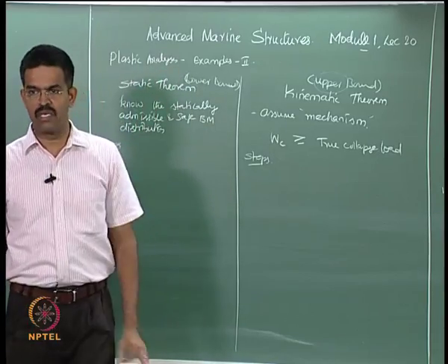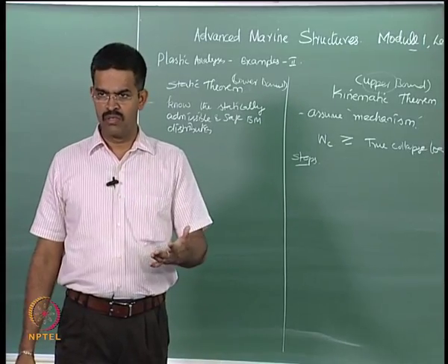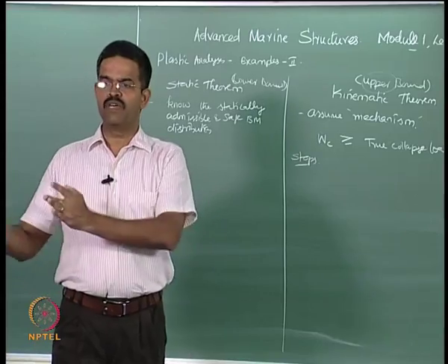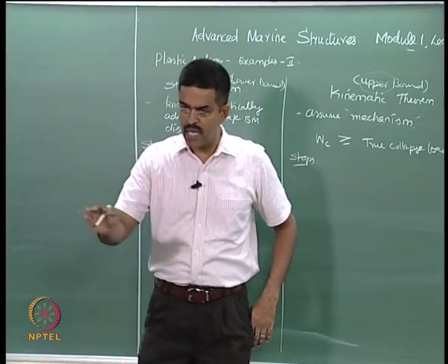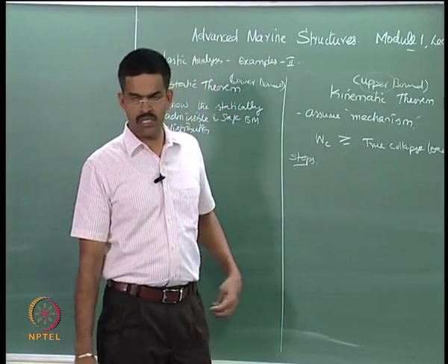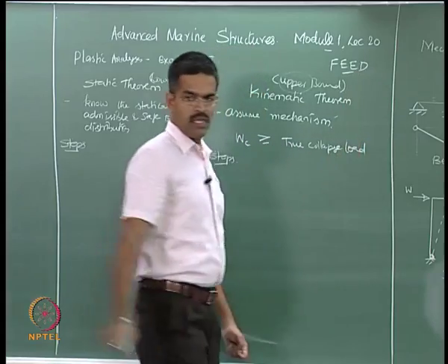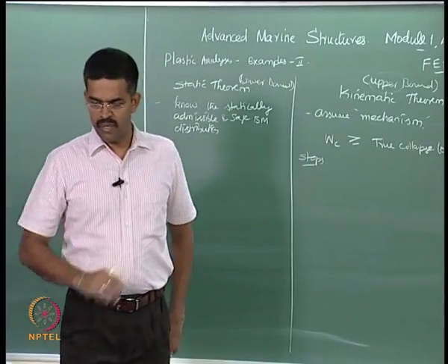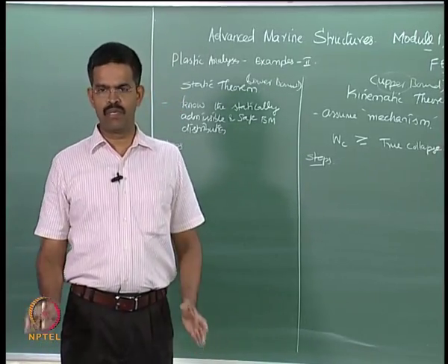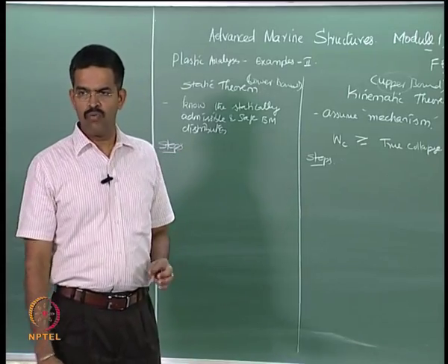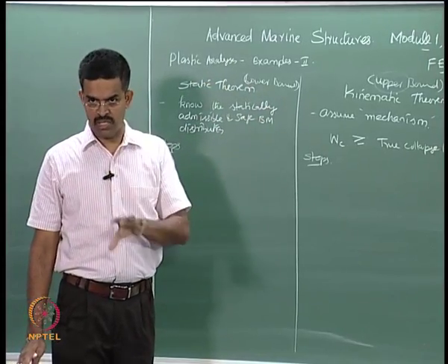Plastic analysis is not a technique which will help you to choose a structural form. Structural form is chosen for marine structures depending upon the functional requirements, where water depth is to be provided, what other kinds of loads are coming onto the structure, what deck area is required, all these are covered in what we call FEED, that is called front end engineering design. So we do this and check the layout of the platform, select a form, a geometric form, a structural form of the platform. So for all practical purposes, to do a plastic analysis, the structural form and the load coming onto the structure are available to me.